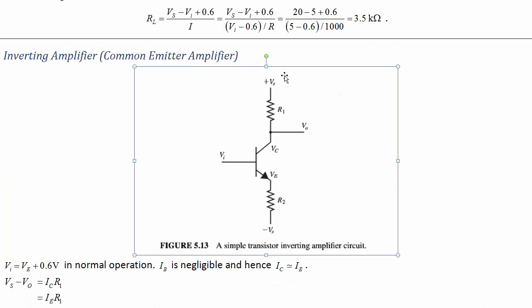What we definitely want is our supply voltages to be as far apart as possible. Other things equal, that's going to increase the range that we can have on our input signal to get an output signal. But the problem with that is that the bigger the voltage difference, the bigger the power, the bigger the passive current we're drawing through the transistor. So you don't get that for free. It's going to be draining more power while we're doing that amplification.